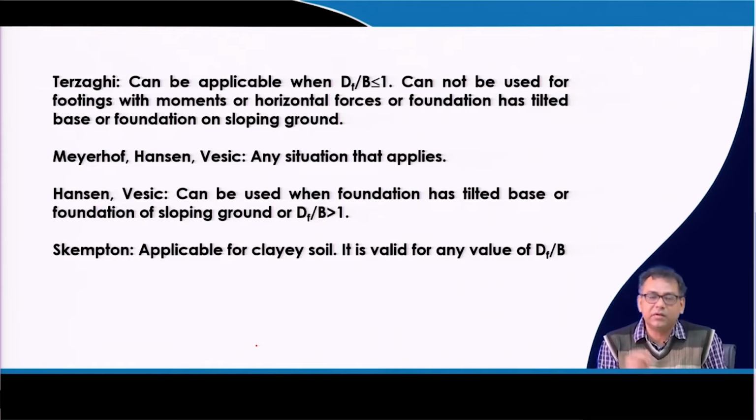So, that means you cannot say which equation I should use always. No, there is no such condition, it is depending upon your requirement. In general, Meyerhof, Hansen, Vesic can be applicable for more or less all the cases, but Skempton is only applicable for clayey soil, and in my next design problems I will prefer to use Skempton if the soil is clayey soil.